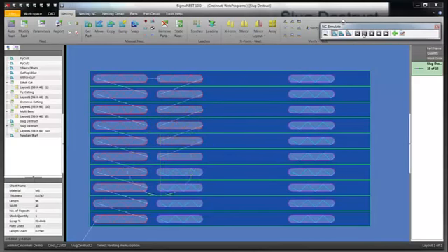the tool path and how we cut these parts out, these internals are going to be important. It's important that we don't go horizontally down here, to avoid that long rapid down at the bottom. So being able to move up and down these things and deal with them in columns rather than rows saves quite a bit of rapid time. Now once we have this last internal cut out, we're going to common line cut the rest of the parts as we zigzag our way down through the bottom.